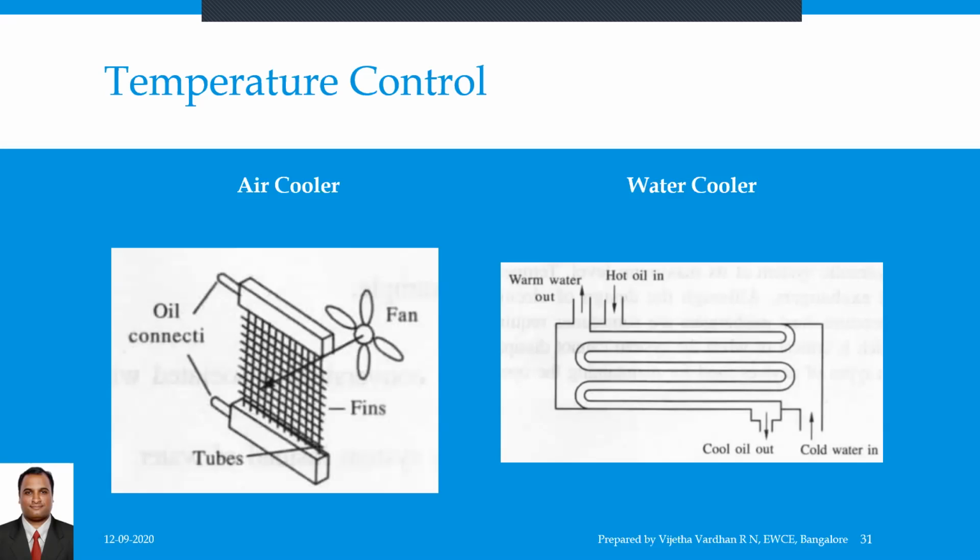Heat removed from the fluid by the water can be regulated thermostatically to maintain the desired temperature. Clean water should be used to prevent the cooler from clogging. By circulating hot water instead of cold water, the heat exchanger can be used as a heater.